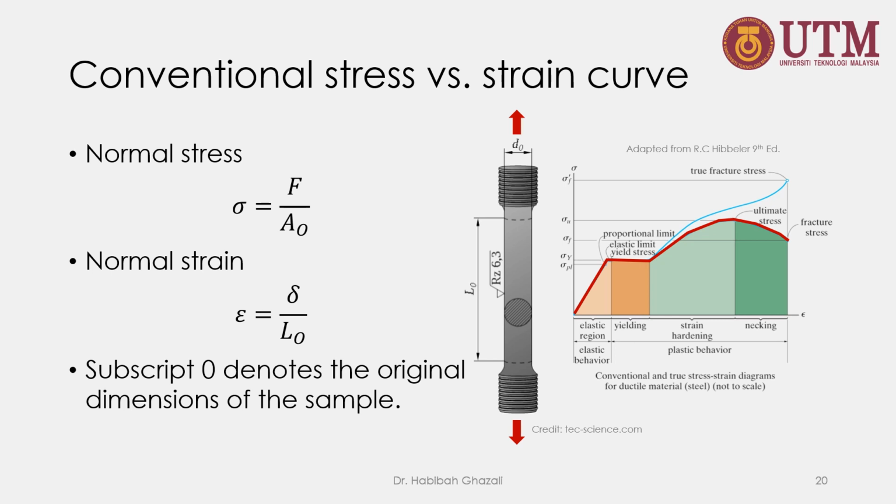So the two stress-strain curve diagrams for any particular material will be quite similar, but they will never be exactly the same. This is because the result actually depends on variables such as material composition and microscopic imperfections. There are no two specimens that can be exactly the same in terms of their microscopic imperfections and also the way they are processed. Temperature can also affect the result of the tensile test.